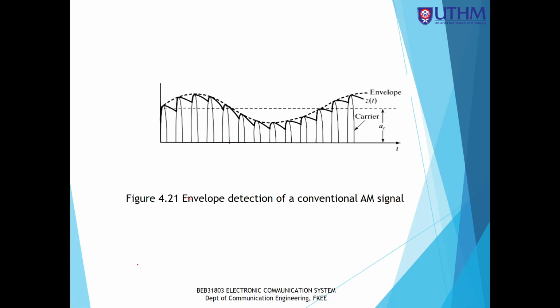So half of it. Remember that during the positive cycle of the signal, which is this one, the RC tank circuit will be charging, and during the negative cycle, the RC tank circuit will be discharging. Due to the RC tank circuit, it will prevent the signal from going down towards the negative cycle. Instead, it will slowly vary the output.